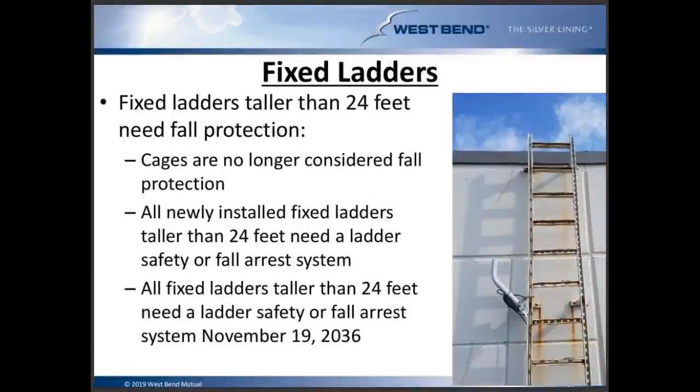So we'll touch on fixed ladders as well, and the main thing I wanted to touch on was the different requirements now under the walking working surface standard for fixed ladders. Cages were the big thing for ladders. I think over 20 feet tall we needed cages. Now there have been some changes to that. Fixed ladders taller than 24 feet, the cages are no longer considered fall protection,